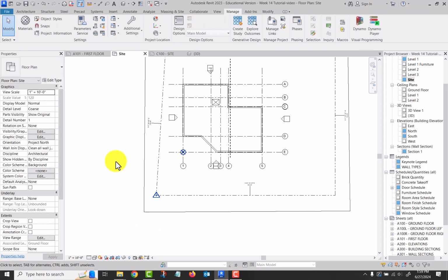Okay, so I would recommend getting the project base point and your building in the right location at the very beginning of your project. So that means when you start drawing your first grid lines, you make them intersect on the project base point, and then you pin those two things. Then you draw your other grid lines the correct distance out. Okay, so those are those kinds of things.